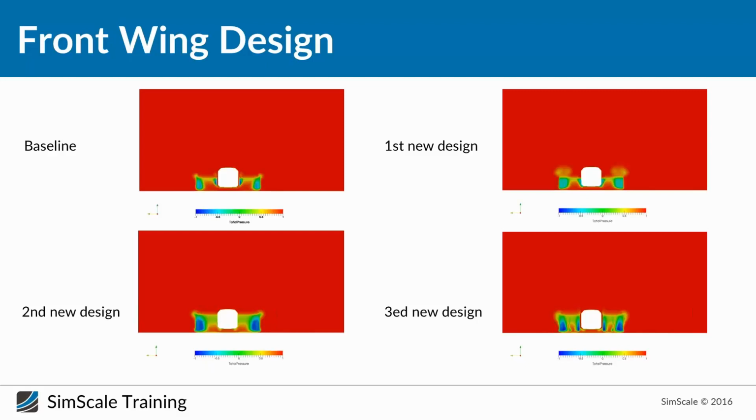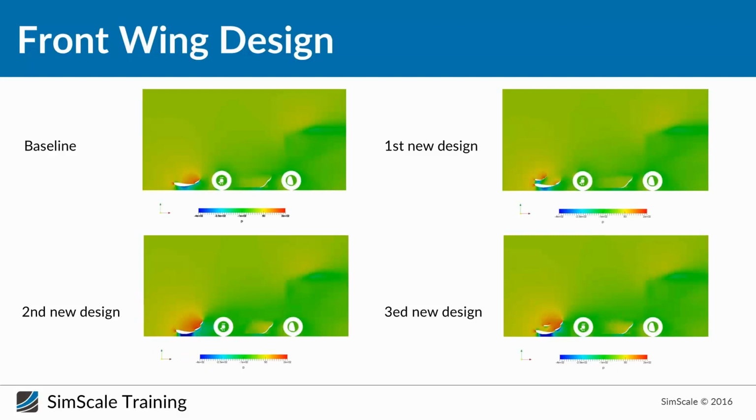Well, just to say that obviously these plots show very well that the bigger the front wing, the worse the energy going to the back of the car, because there's less and less red, so it's pretty clear. Which is why, again, you have to be really careful with pushing the front wing more. You need to make sure that it works with the way you want to balance the car, because you will lose rear downforce for sure. Mm-hmm. That's right.